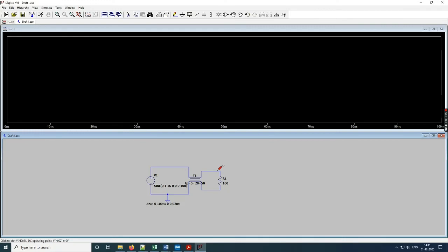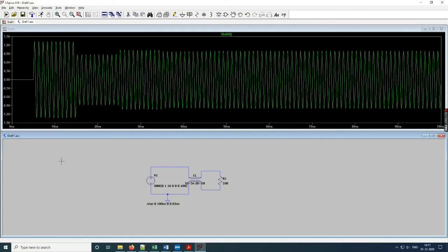So the moment I put the marker across the load, this is what I see. Now you observe something very interesting. This is a plot of voltage versus time. For the first 5 nanoseconds, there is nothing across the load. Why? Because the wave takes a minimum of 5 nanoseconds to travel from the source to the load. So therefore, obviously, you will see nothing at the source side.